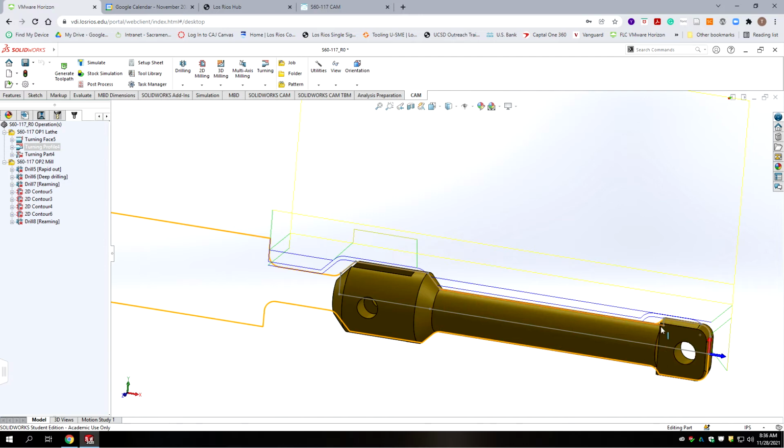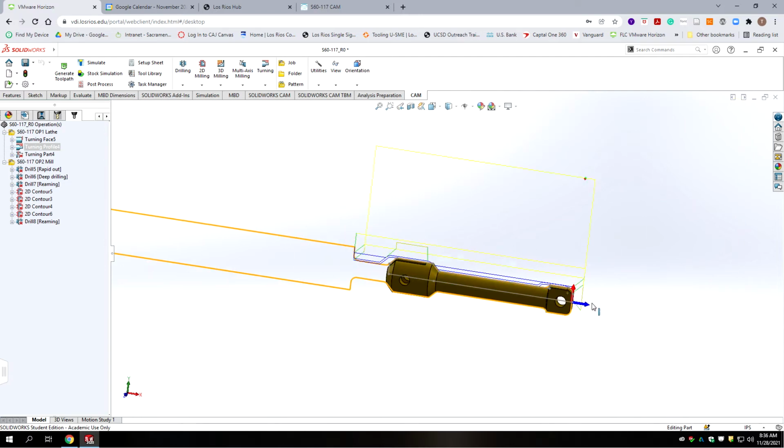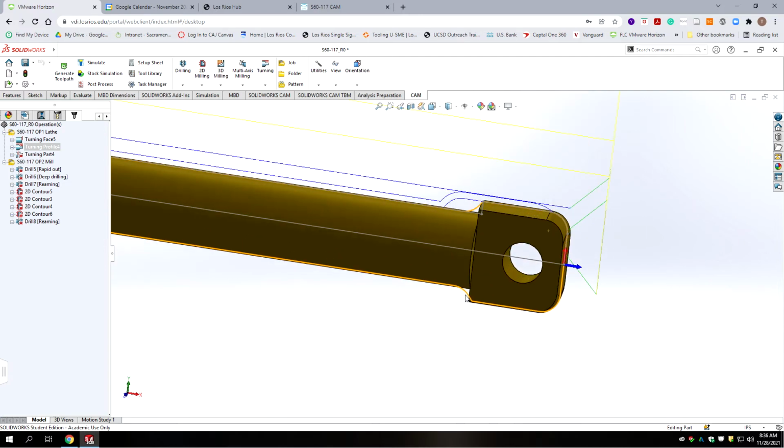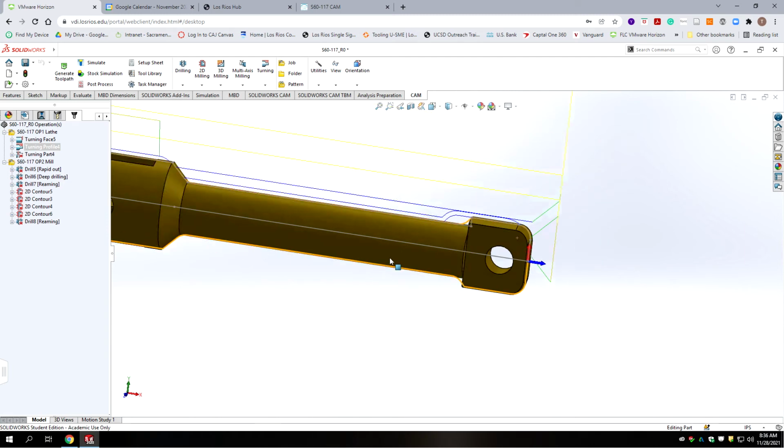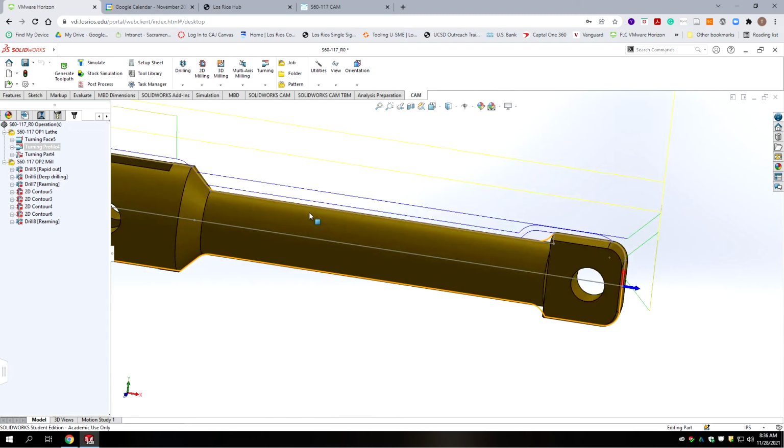What you need to do is sharpen up this corner. You see there's a substantial fillet, and we have it sharp, and we're going to end up with possibly some issues there with fit. So we need to go in with a square shaped grooving tool, and so we need to add that to this routine, and we had one.